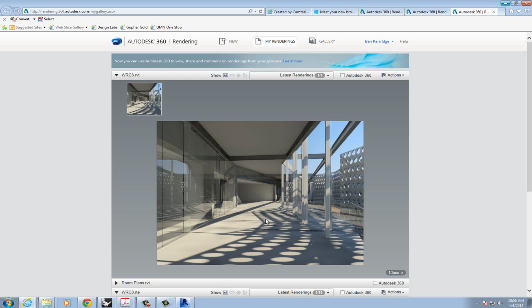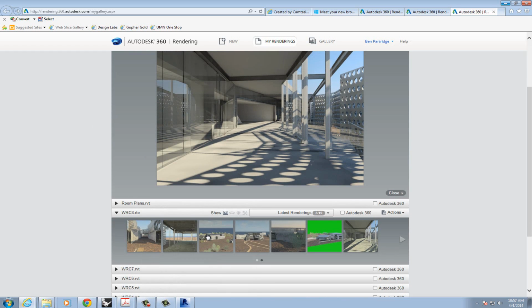Right. So we just redid the rendering of the concrete, so it no longer shows the pattern that we had on here. You can sort of see these streaks back and forth, but again, you have to adjust the size if you want to see it a little more clearly. It gives us another finalized image, and it replaced the one that we did. So if you want a new image but to keep the old one, you have to either duplicate the viewport or have a new camera angle, because sometimes you may want to come back to the original image. You can always save it before you re-render it, but it's going to re-render it.